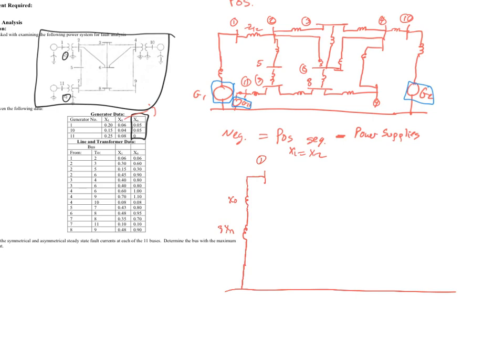Now we continue on and we see that we have a delta connected transformer, and if you look at your table, no zero sequence current can enter or exit the transformer, so we're going to draw that as an open connection. On the other side, we see that it's a grounded Y, which does allow us to have zero sequence current flow as long as the other side does. Since this is a delta grounded Y, we actually do have an impedance here. And since there's no impedance there, that's just going to be shown as a solid connection. So we come up from our reference, and then this becomes our bus number 2 as shown there.